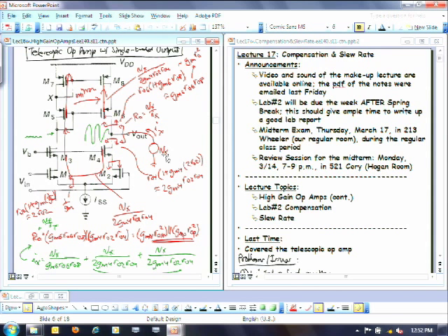You know you have some current going up this way into this cascode network, but you also have some current going down this way, which in a small signal sense wraps around and then gets mirrored back out here, to the point where you end up seeing a resistance that's just this cascode in parallel with what looks like just that cascode. Yes?